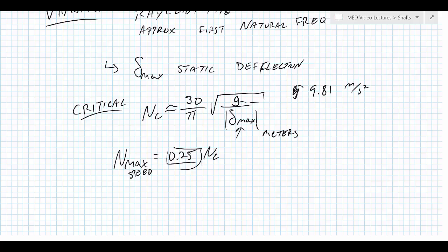The other special part of shafts is that because we've got elements spinning at high speeds, they have this ability to both deflect and wobble. So we want to make sure that whatever static deflection, even if it's well within the elastic region of our part, is not going to cause problems with other components on the system. That, of course, depends on what components they're talking about, as well as avoiding this whirling, wobbly behavior that happens when we get to the critical speed. When you do calculate deflection, you may find that the critical speed is surprisingly lower than you might think.